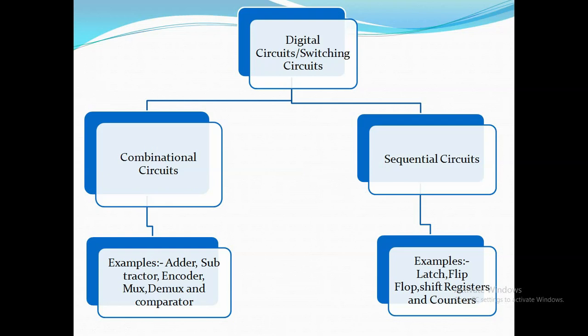It is the basic storage element in sequential logic. Flip-flops and latches are fundamental building blocks of digital electronics. Such systems are used in computers, communications, and many other types of systems. Flip-flops and latches are used as data storage elements. A flip-flop is a device which stores a single bit, that is a binary digit of data. A flip-flop can be either level triggered, that is asynchronous, transparent, or opaque. The term flip-flop has historically referred to both level triggered and edge triggered circuits.